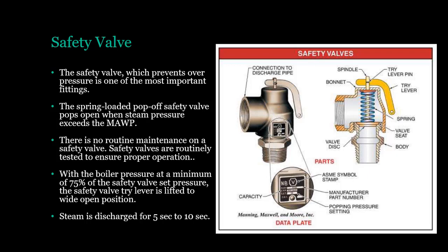With the boiler pressure at a minimum of 75% of the safety valve set pressure, the safety valve tri-lever is lifted to wide open position. Steam is discharged for 5 to 10 seconds.